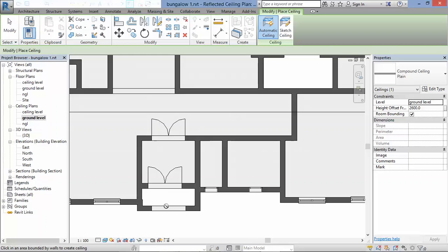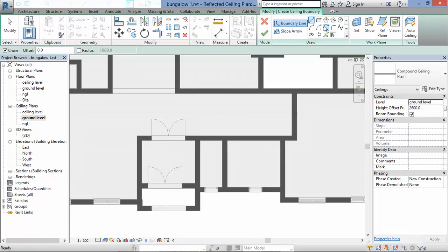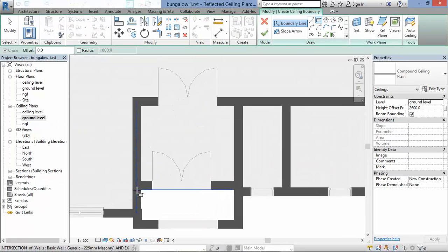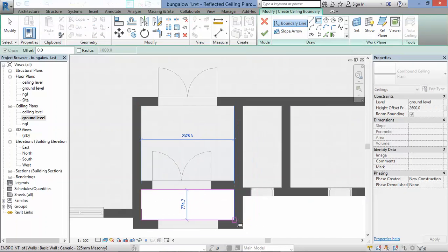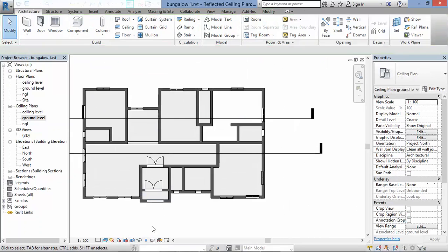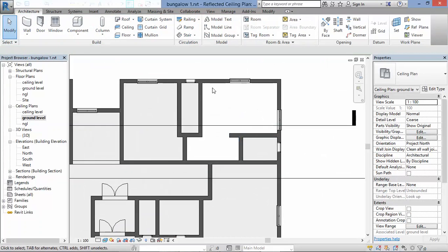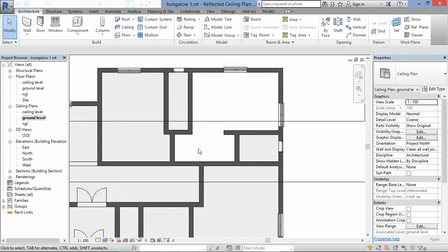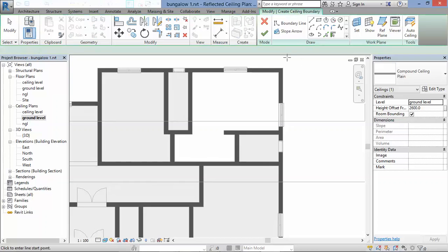So for you to create your own ceiling here, what you do is you create a sketch. I'll go to my sketch and create my ceiling. That's if I want a ceiling on the outside. Then I'll say okay. You can see it is not there. Same thing with this one. It's not properly enclosed somewhere. I don't know where that would be, but let us create it using our sketch.